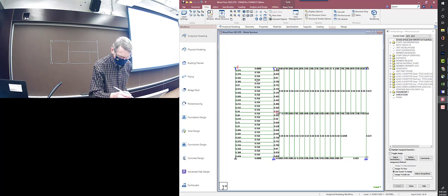These are the joists, I guess. If I'm seeing them right, yeah, this should be the joist. This is the beam, this is the beam, this is the joist, rafters rather. So the rafters are, if that number is correct, way over designed. They're only like at 10%. Okay, so they're way over designed at a 2x10. Maybe go down to a 2x8 or a 2x6. These are not quite so over designed. I think I had both of them as a 2x10 originally, right? So maybe we could make this one a 2x8 and this one a 2x6.